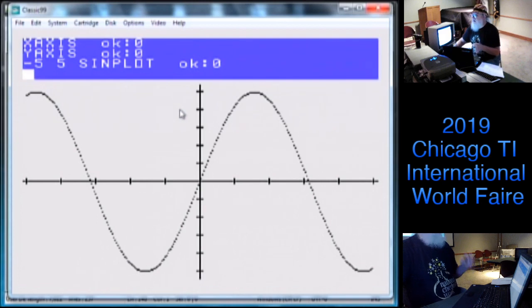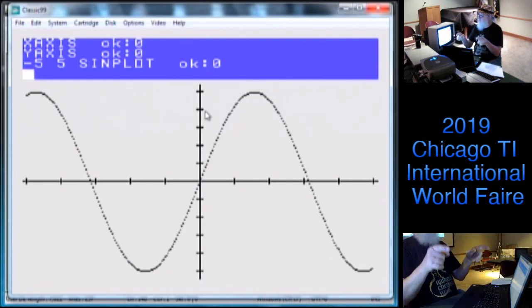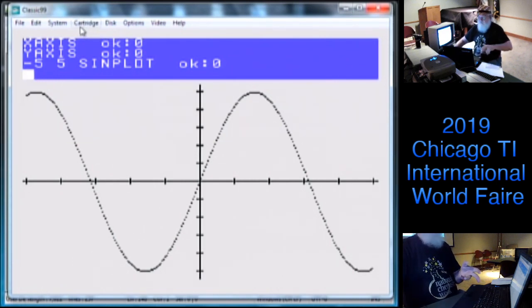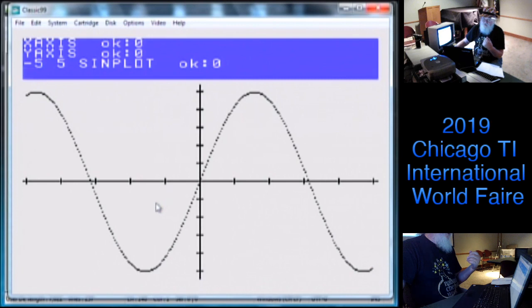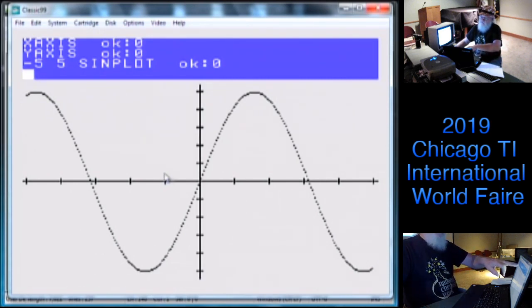So now the pattern descriptor table is 8 times that, because you have to have 8 bytes per character to define it. So you have 6144 bytes in the pattern descriptor table, and you have the same number for the color table, so that you can define each set of 8 bits differently. To deal with characters, you can use the 8 by 8 that you see at the top here.